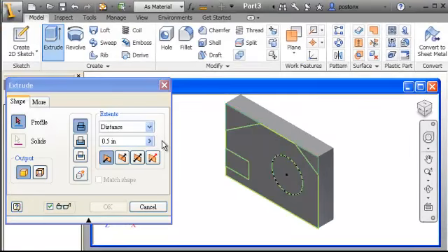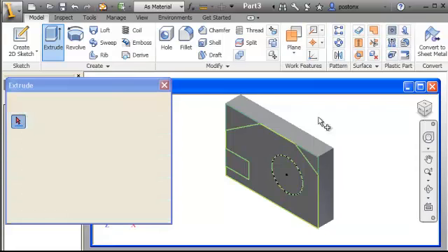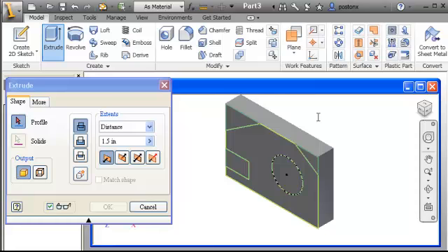Okay, little drawing over here pops up. I like this little drawing over here because I'm always right on the project looking at it very strenuously. Okay, we want to make this one like, let's go up here and just make this 1.5 inches so we know we cut through and we didn't leave a hairline on the other side. Because sometimes pixels little crazy. Okay, what do we want to do here? We want to do a cut. So we want to do direction number 2. Okay, direction number 2 gives us a cut. And there's our cut. Okay, it looks good.